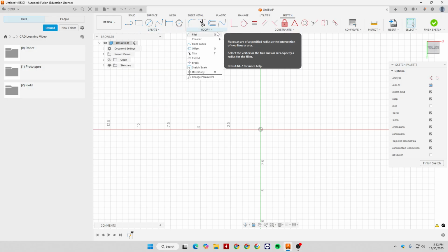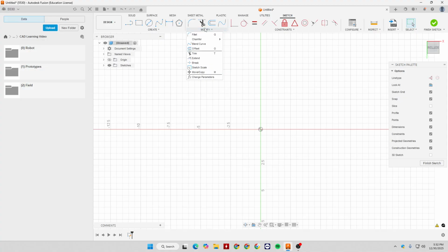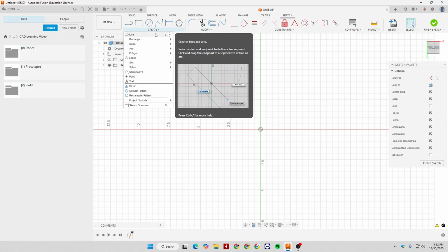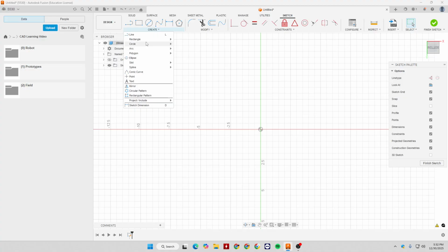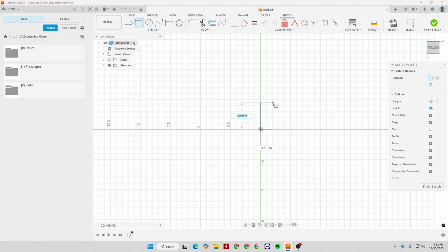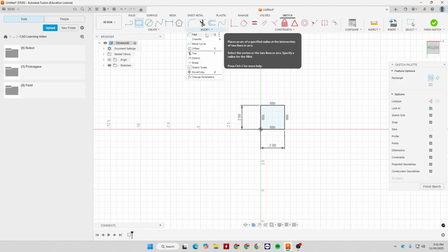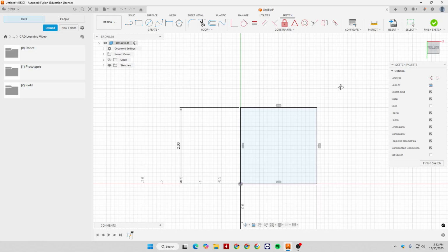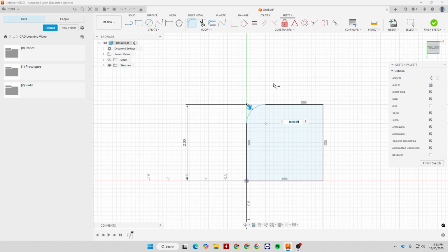So we're going to move over here to kind of our editing tools. We're going to put down a rectangle here, and we can actually define that instead of just leaving it like that. We're going to do a 2x2, and we're going to start off with our fillet, which is bound to my G key. And this will make the corner round with a specified radius. So the radius of the circle right now is 0.5 inches.